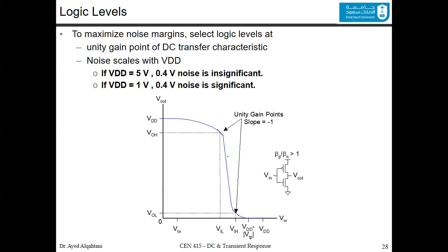So it's more than 1. So it was pulled from the center in this direction. What happens is, comparing these values, you can see you have certain slopes here at this point and this point because of this pulling. And now you have a VOH over here and the VOL is over here. You can see compared from 0 to VOL is very small. And here, compared to that part, it's kind of large.